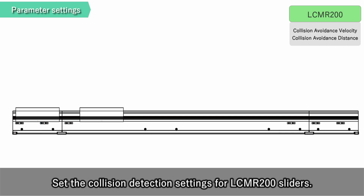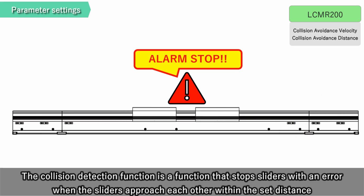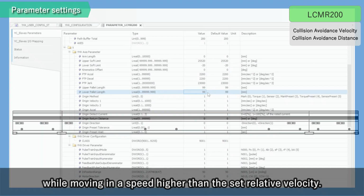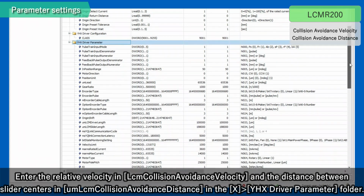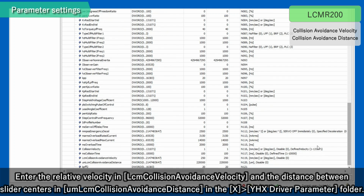Set the collision detection settings for LCMR200 sliders. The collision detection function stops sliders with an error when the sliders approach each other within the set distance while moving at a speed higher than the set relative velocity. Enter the relative velocity in LCM collision avoidance velocity, and the distance between slider centers in LCM collision avoidance distance in the YHX driver parameter folder.